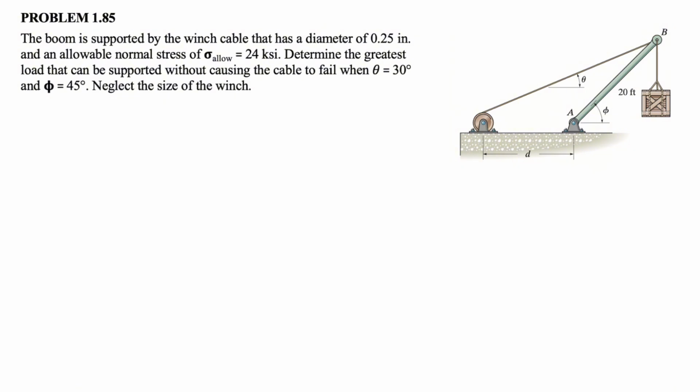And we can neglect the size of the winch in here. So if that's the case, basically, we don't consider any diameter for this winch that we have in here, just to make the calculation a bit easier. And so basically we have one condition in this, and that would be the normal stress in the cable.